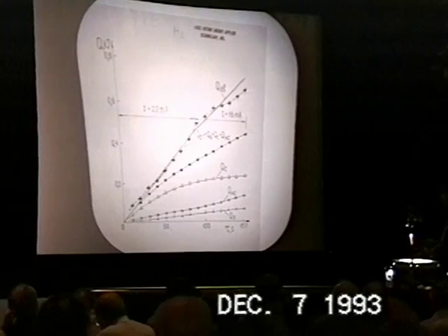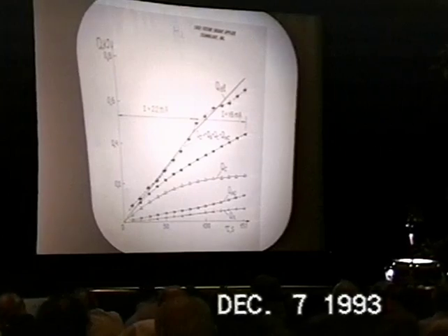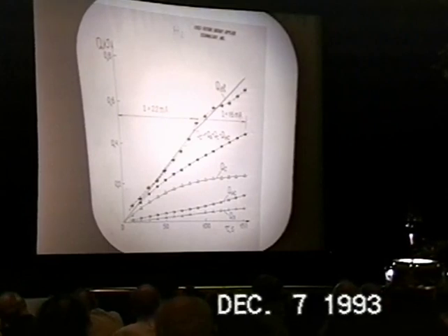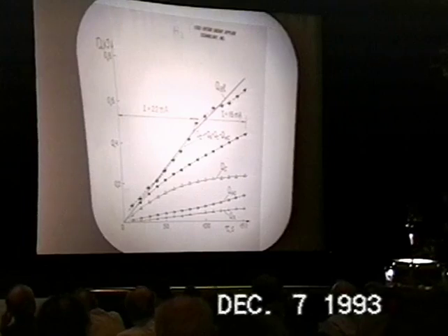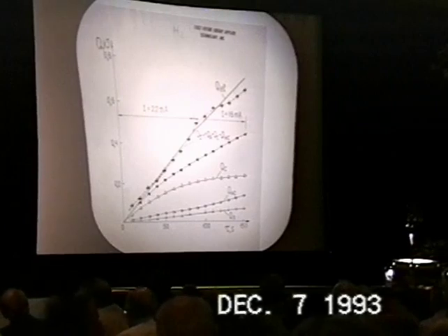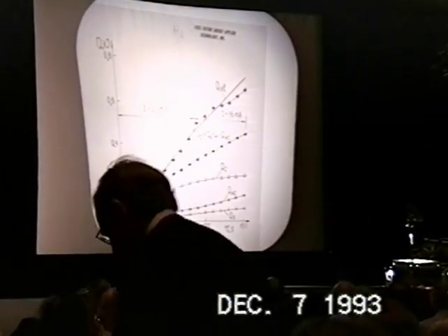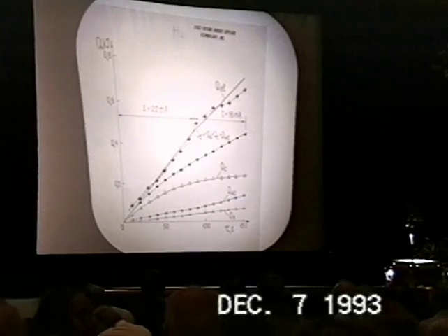So this calorimeter consists of 3 parts, and each part has its own contribution in the calorimeter measurement system. So it is the heat measured by the anode part, the heat measured by the heat collector, and by the cathode. Here are the signals of all 3 parts. It was well known from the literature, but here it is also clearly shown that most of the heat in this type of discharge goes into the cathode. So the heat flow in the cathode is higher than it is in the other 2 parts.